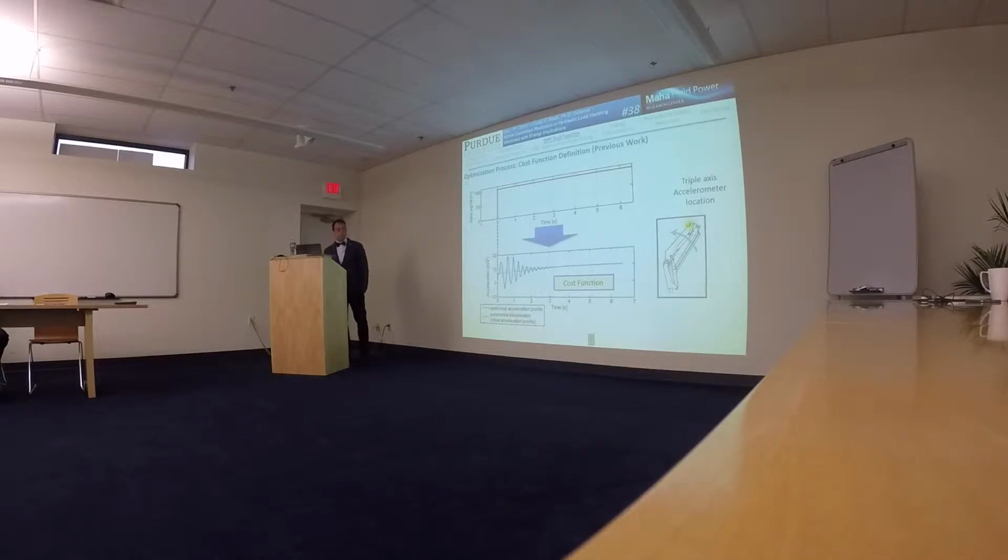And I want to spend a few words on this cost function calculation, because it's a very clever way to define a cost function, because as you can notice, the acceleration oscillation is not around zero. It has a varying offset. And this is because the accelerometer on the machine can actually also feel the gravitational acceleration, which intrinsically is also giving information on the position of the boom.